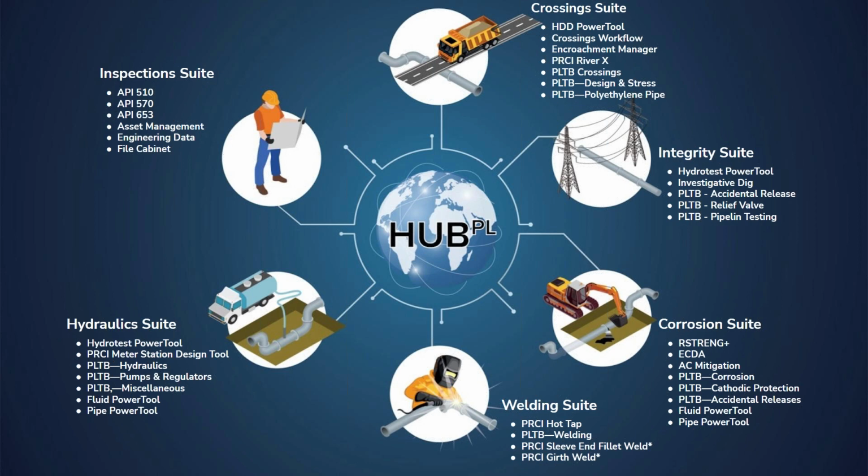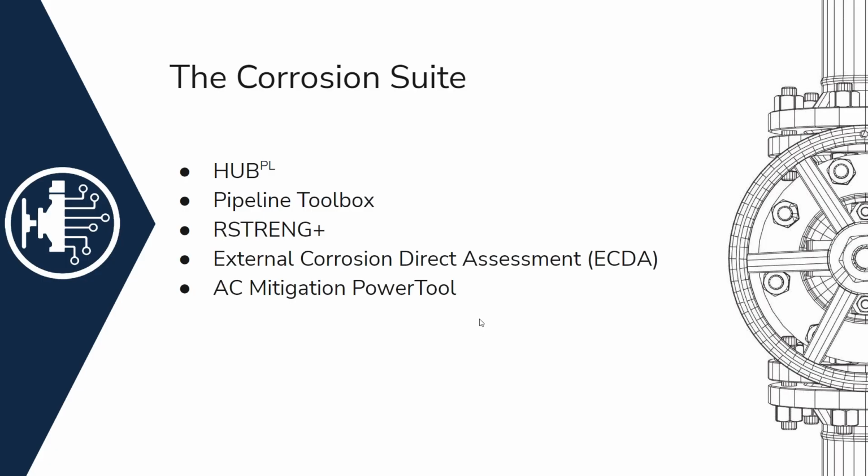So the solutions are simulating. We should be able to simulate these and optimize these repairs. Determining the reassessment interval: if we have a certain corrosion rate, and we're not slowing it down, whether it's internal or external or both, they could be two different ones, and we're not controlling that, then we're losing our grip on it.